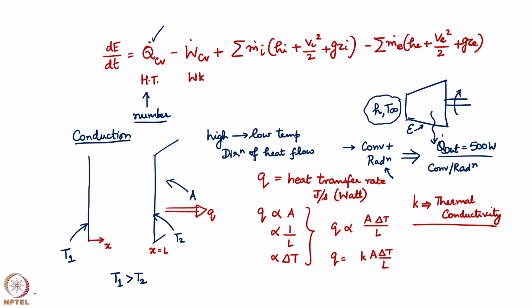Thermal conductivity decides how fast or how slow the heat is going to get transferred. So if I have a pan, for example, made of copper at the bottom, you don't have the handle made of copper. You have the handle made of typically wood. Why? Because when this pan gets hot, the handle still has to remain cold. That means with wood, though the heat is coming onto the pan, very little heat is coming to the wooden handle. Therefore, this wood is going to have a very different value of thermal conductivity, which is a material property, compared to copper, which has a very high value.